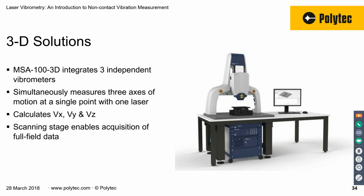This is an example of a 3D vibrometer where we're measuring vibration from 3 directions at a single point. In this case, we don't have 3 lasers aimed at the same point. We have only 1 laser, and we have 3 interferometers that are aimed at that point. So again, through triangulation, we can extract velocity vectors x, y, and z. And here we have a scanning stage, so we can actually scan the device under the laser beam and map the 3-dimensional vibrations over a full surface area.